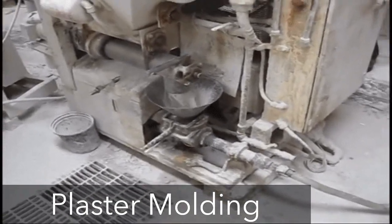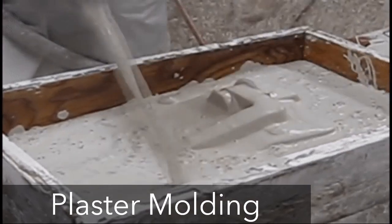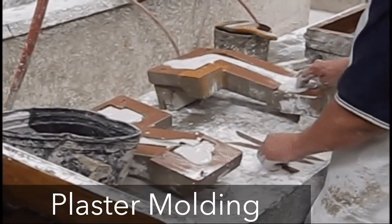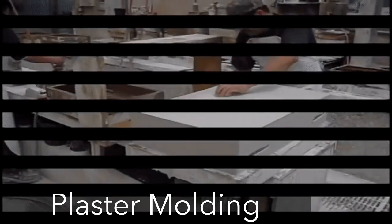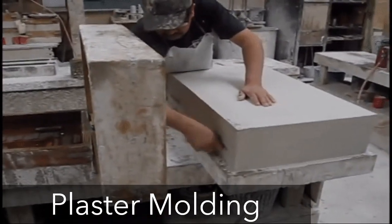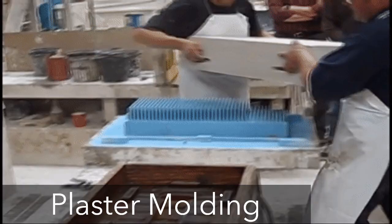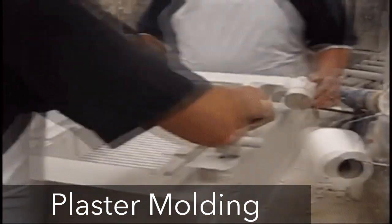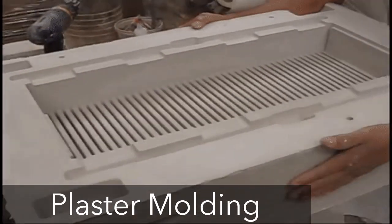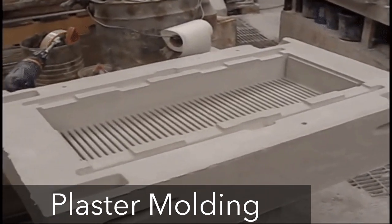In the plaster molding process, the mold is made of plaster of Paris, which is known as gypsum or calcium sulfate, with the addition of talc and silica flour to improve the strength and control the time required for the plaster to set. After the plaster sets, usually within 15 minutes, it is removed and the mold is dried at a temperature range of 120 to 260 degrees. Higher drying temperatures may be used depending on the type of plaster, and the mold halves are then assembled to form the mold cavity and preheated to about 120 degrees. The molten metal is then poured into the mold.